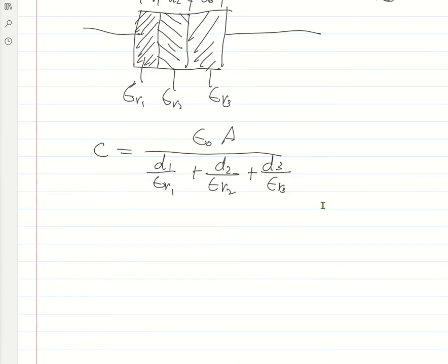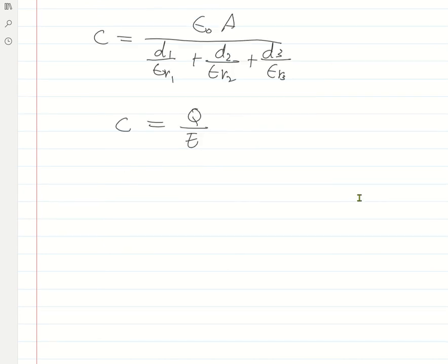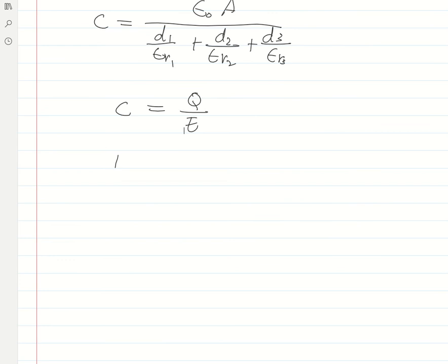Then also we can derive the voltage across the capacitor or the current across the capacitor, taking the formula for the capacitance, C equals Q over the voltage across it. So if we want to determine the current, remember current is just equal to the rate of charge with respect to time, I equals dq dt.